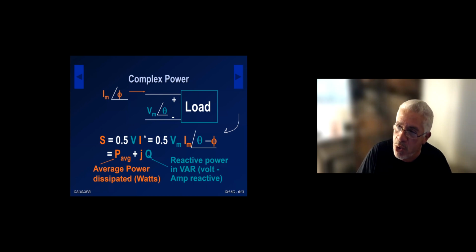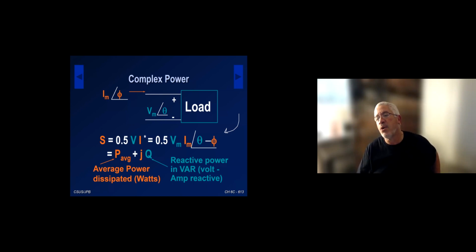So we're introducing a new power here today. Beside the complex power, we're going to introduce the so-called reactive power, which is the imaginary part of the complex power. The imaginary part of the complex power, we call it Q. Its unit is going to be volt ampere reactive.